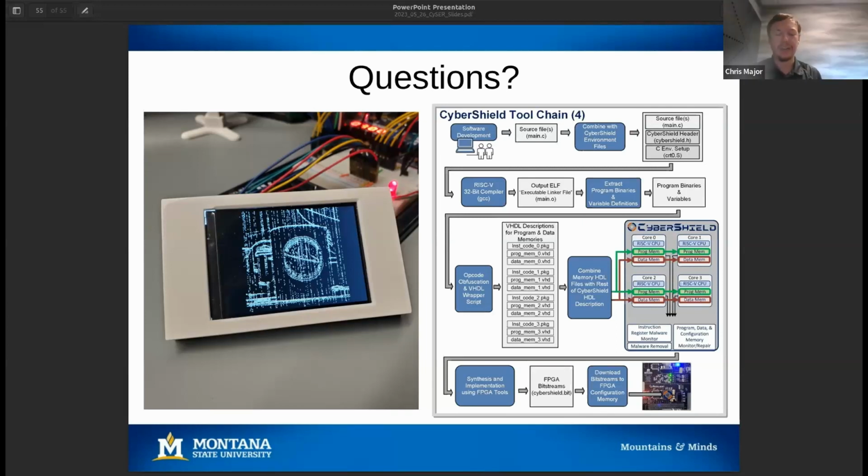Yeah, the malware affected core is salvaged. I don't think I explained that too well in the video segment, but one of the RADPC recovery mechanisms that we brought into the project allows us to go back through the memory and fix all the bad values by comparing them with a copy. So that 4th core is salvaged and brought back to reset, so that it can catch up with the other cores and the whole system keeps running.